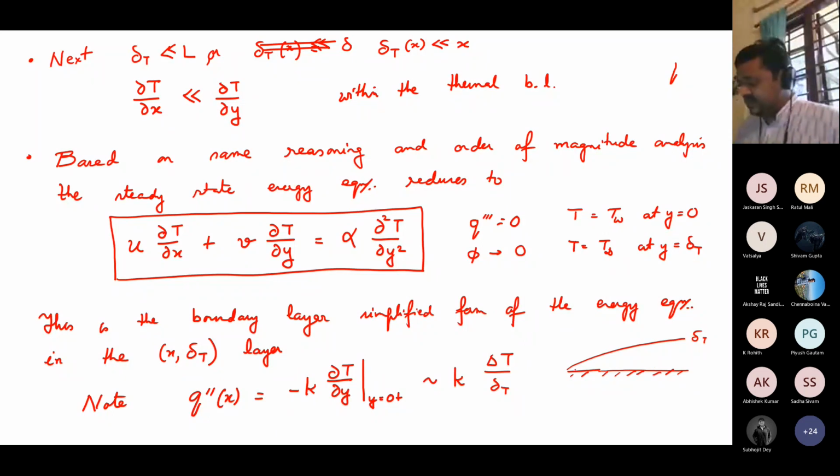So definitely, you can say that the heat transfer is going to be higher at lower values of x and lower at higher values of x. That way, it's a little different. The dependence is kind of inverse to that of shear stress. For shear stress, the higher the velocity gradient, and therefore the lower the momentum boundary layer thickness, the higher is the shear stress.